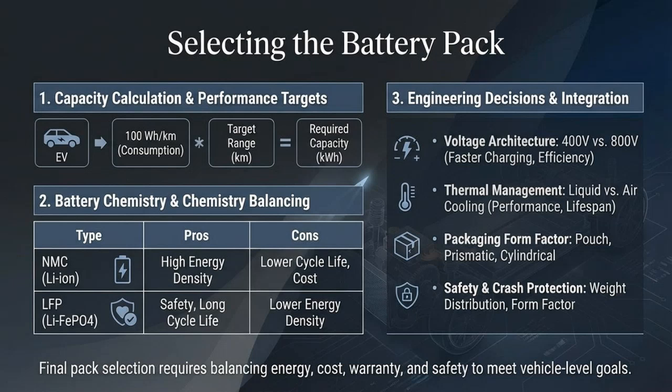The next decision is battery chemistry. Lithium-ion NMC is preferred for high energy density. LFP is used when safety and long cycle life are priorities. Solid state is emerging, especially for premium applications.